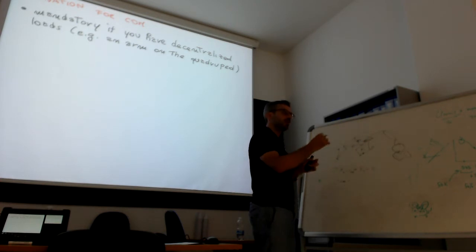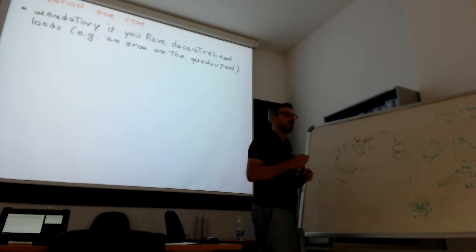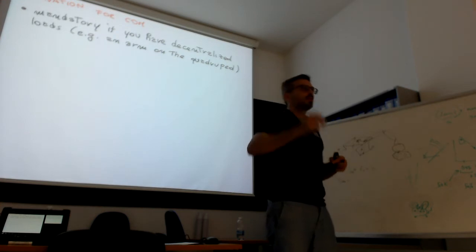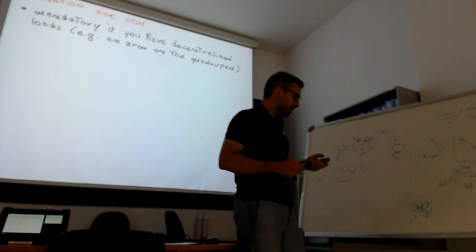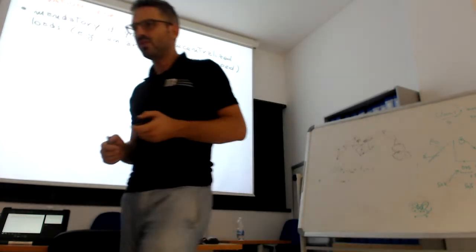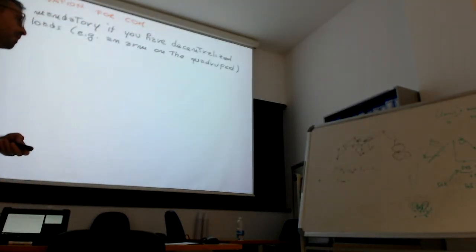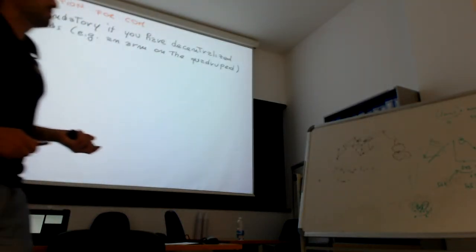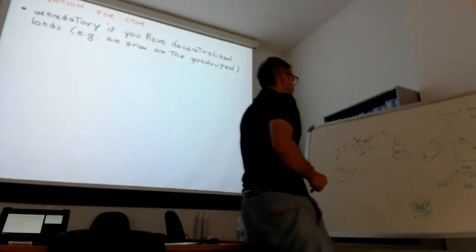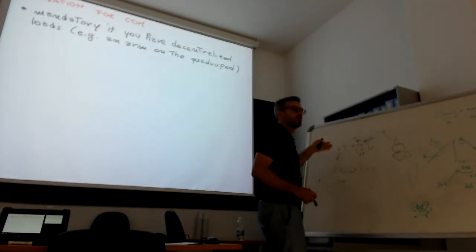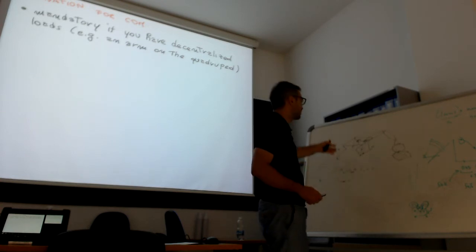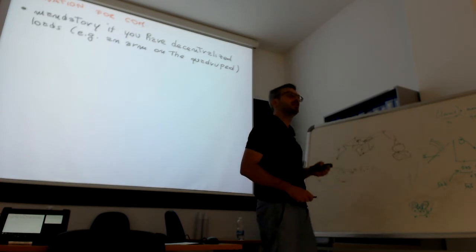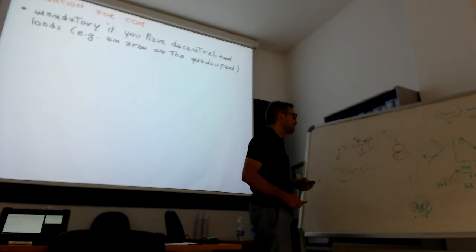So it will move in a recursive way till you reach the estimation. It's written in a paper on load identification of 2017. We did this work, it's quite okay. The problem is that it relies on the contact force estimation, so if you have modeling error in the contact force estimation, you have inaccuracy in the center of mass estimation.